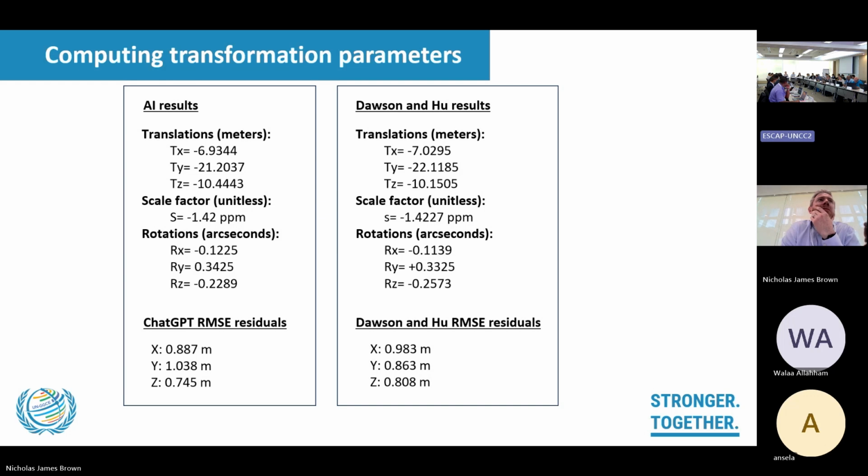Of course, it's a recursive process because we don't have that information. So we just have to assume that the Australian National Spheroid was the best fit of the Australian PNG region, and that the N values would be quite minimal, because that was the way it was designed, to minimize that separation. So we just basically said that they were ellipsoid heights.